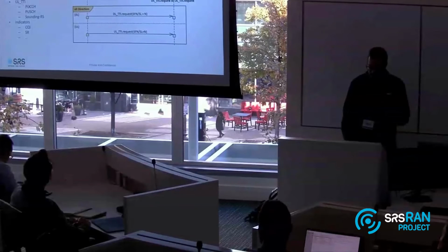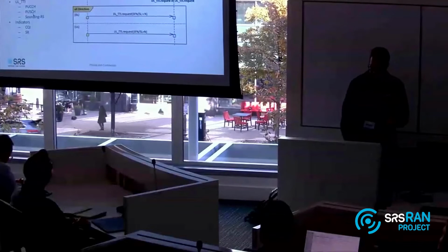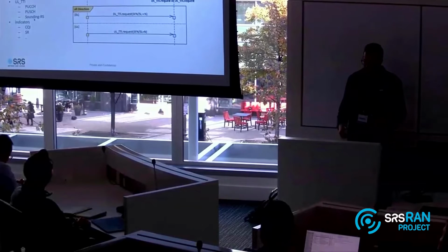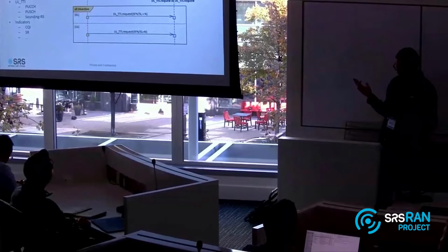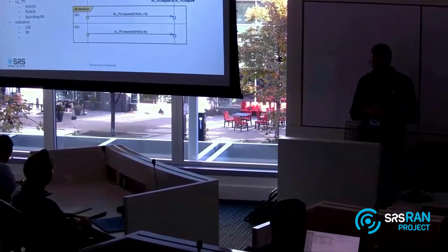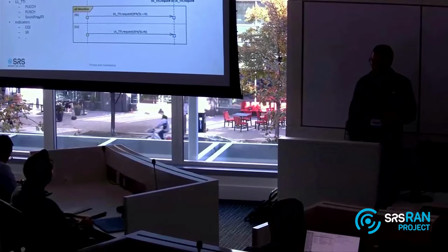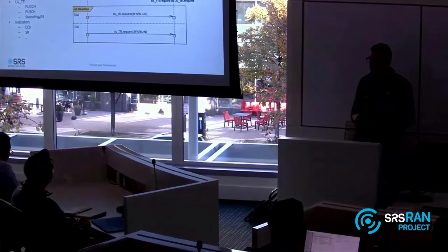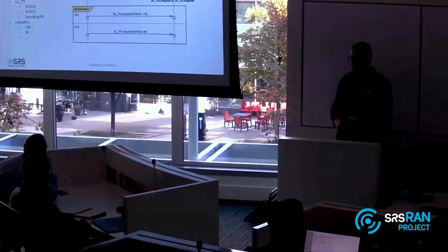So if you want to experiment with these kinds of things. The uplink TTI messages, in a similar way, tell the PHY what things it should receive on the control channel or on the PUSCH, for instance, or if it should expect sounding reference signals. So again, if you are experimenting with uplink MIMO estimation, maybe you are interested in this. If you want to experiment with what happens with extra custom parameters out of the spec, you would include those in this message and then tell the PHY to use them to receive.